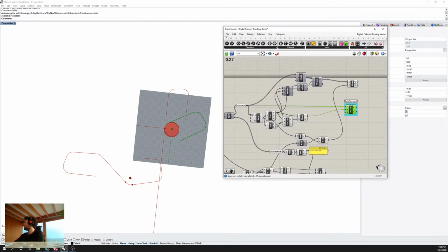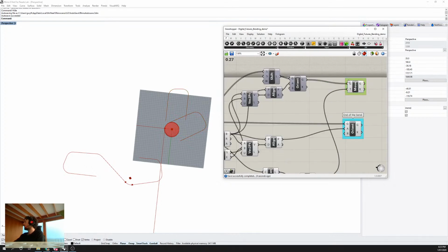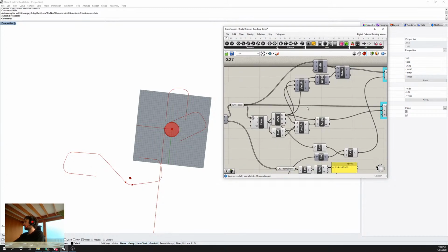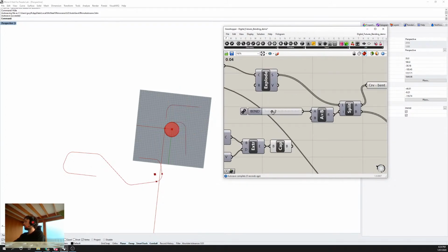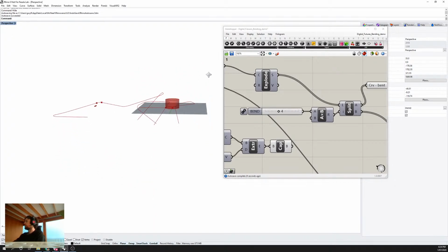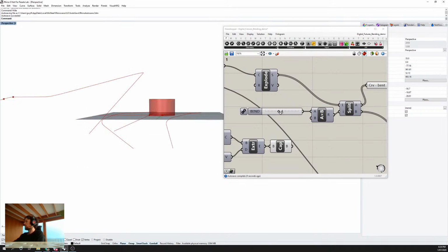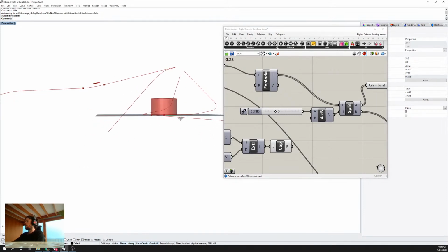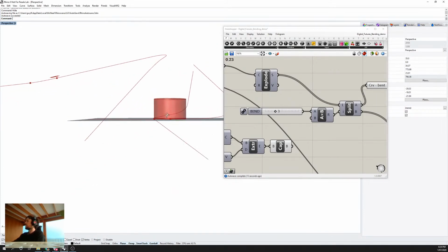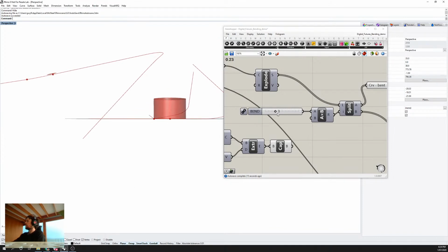We have the end of our bend, we have the start of our bend. We're able to step through and preview each one of these bends. We can see the remaining material. And this works in 3D. So the bend is always in the correct plane, but you sometimes need to rotate the part in 3D to get it to do 3D bends.